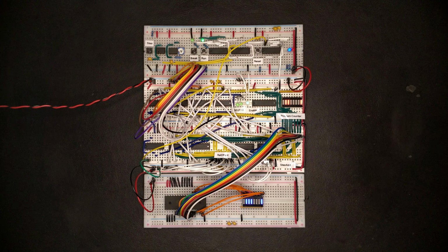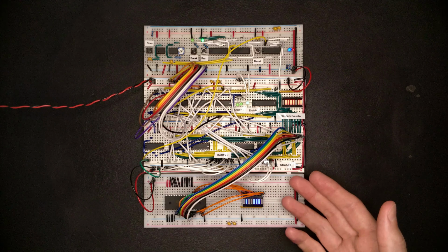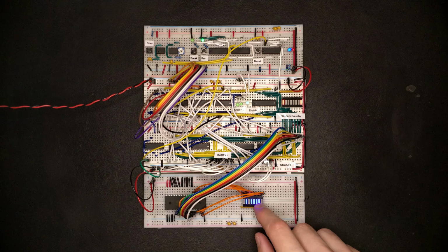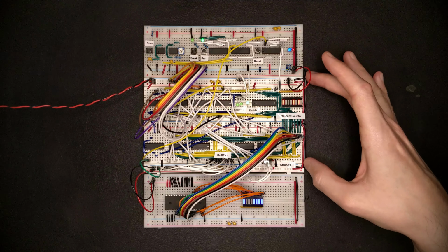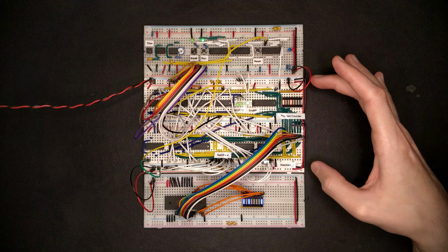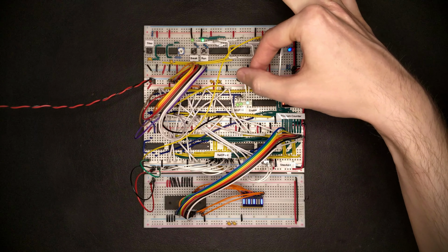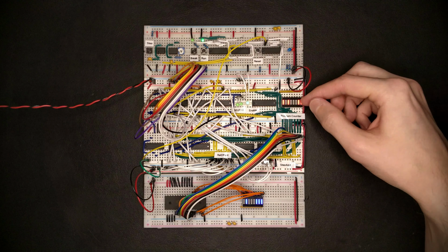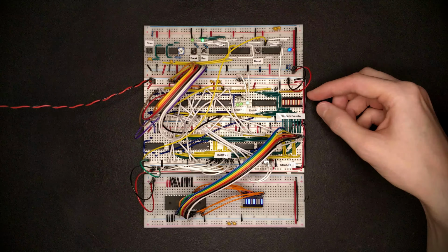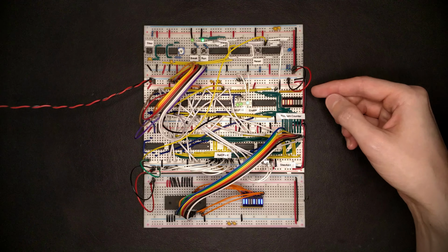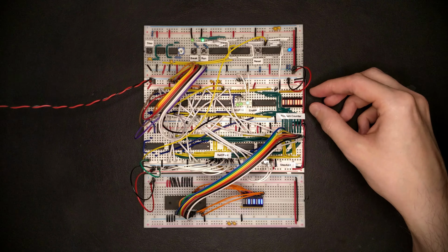Now let's think about how we can actually make this more interesting. Currently we're just reading out memory addresses and producing the data here, but we're not doing anything with it besides looking at them. If we look back up at the program counter that we've been building, there are actually all these control signals like the select line, which selects where the program counter goes next, if it's just the next instruction or if it does a jump.